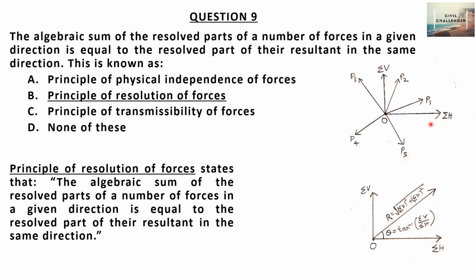Okay, and then we can find the resultant from the principle of resolution of forces, which means that the algebraic sum of the resolved parts of a number of forces in a given direction is equal to the resolved part of the resultant in the same direction. Okay, now if we add the corresponding components of the number of forces along the horizontal direction, then this sigma H, which is the sum of the resolved parts of a number of forces, is equal to the resolved part of the resultant force.